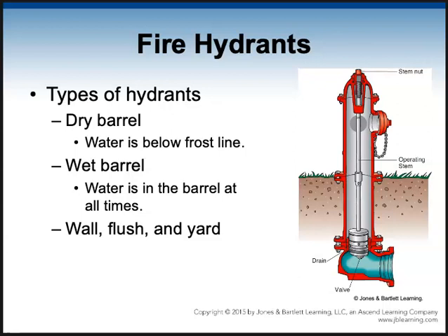A wet barrel, like we have here in most of Southern California, we're in an area where we don't get a lot of freezing, so the water is allowed to be right there, and each outlet can be opened independently. The water is right up to the outlets. Just opening the valve allows the water to flow. The downside of a dry barrel hydrant is once you open the valve, it's there in the whole hydrant. Any cap you take off, water's going to gush out.